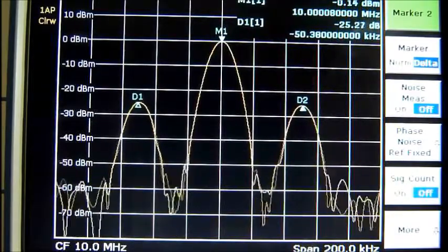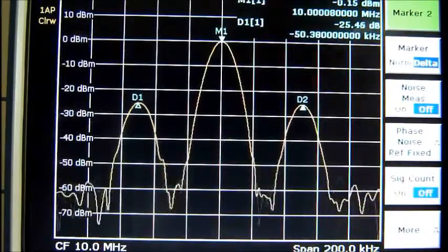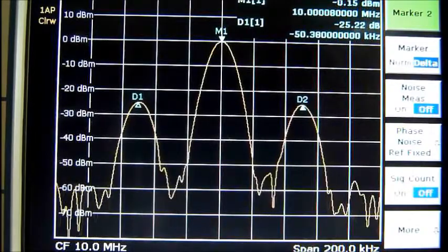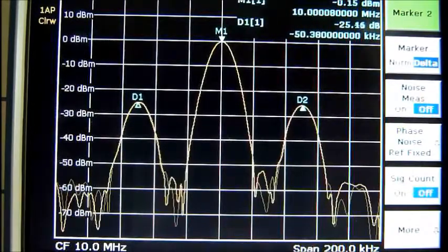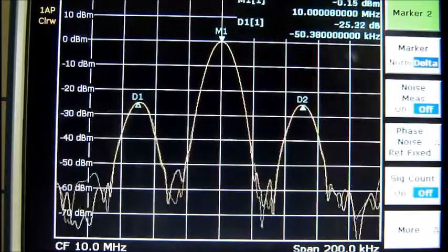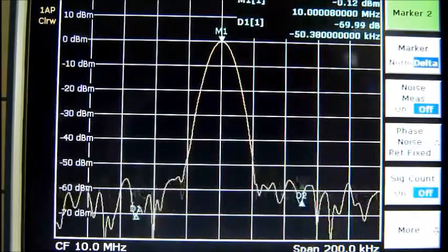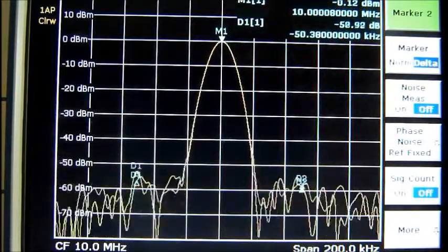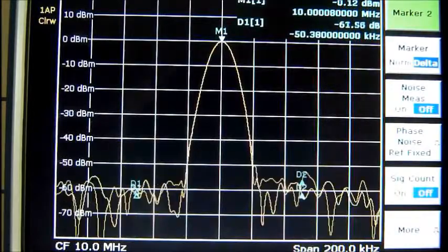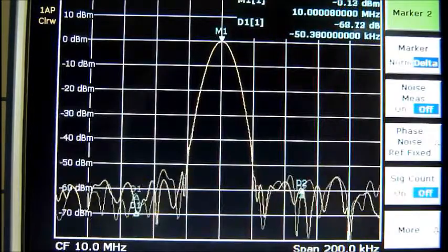The higher the modulation index, the more similar the power of the information signal will be to the power of the total signal. Right now, we have a modulation index of 10% chosen. If we just go down to 0%, we see how the modulated signal disappears and we only have the carrier signal. Why? Because 0 modulation index is equal to no modulation.